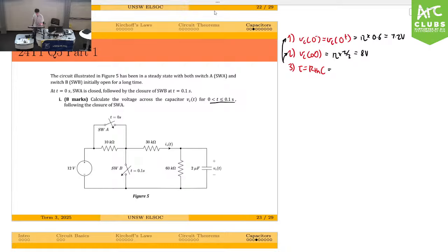And now quickly to find the RTH. When you're finding RTH across these two nodes, looking inwards, we're considering this after we flip the switch. So after we flip the switch, this becomes shorted. We're turning off the source. If you go back to Thevenin's method 1 from Jerry's part, you short the source.